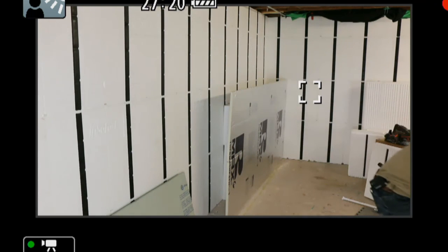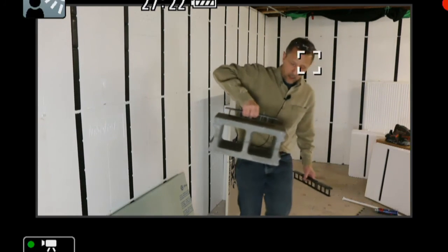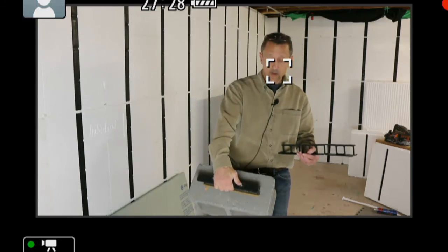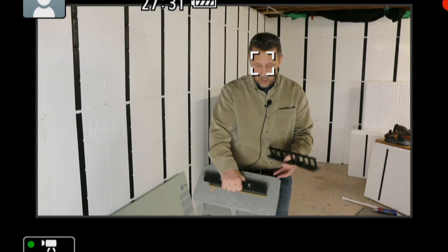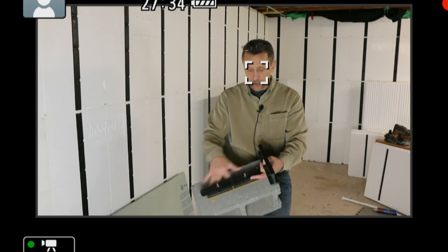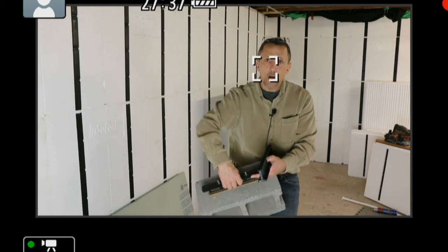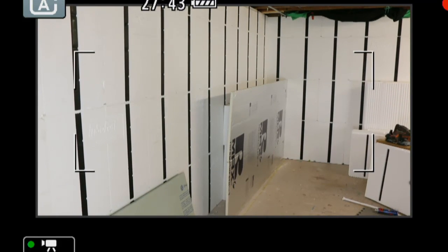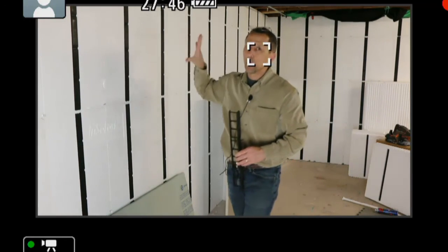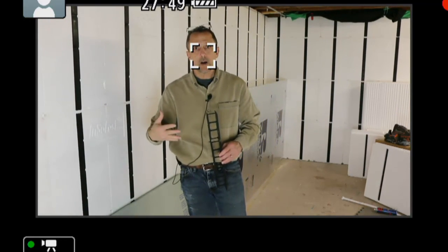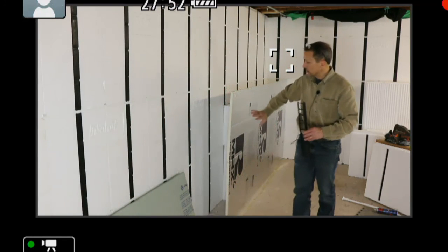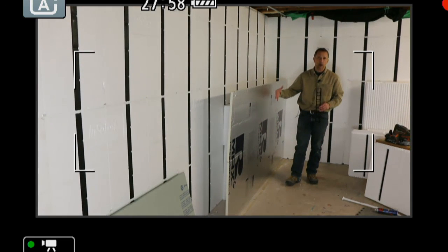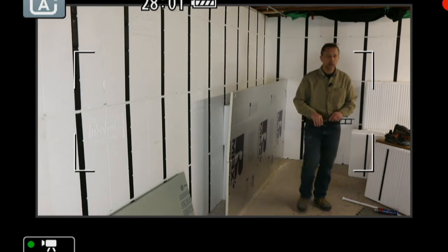So when we glue the stud to the concrete, this is going to hold in place, and the screws are going to hold the drywall in place. This is 108 pounds per lineal inch. This is 12 inches, so that's around 1,200 pounds worth of pull-off. That should be enough to hold any drywall or cabinet that you have. The screw is going to pull out of the stud way before the stud will pop off the wall. But that's how we achieve an R-15, the InSoFast PLUS system, by laminating another manufacturer's insulation panel on top of our insulation, and you can achieve what you need to achieve.